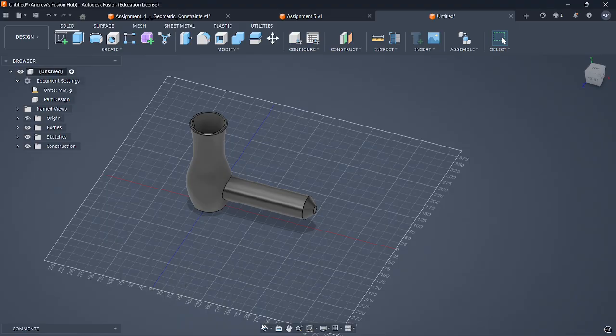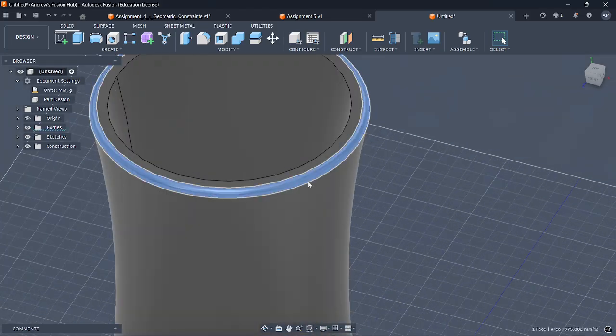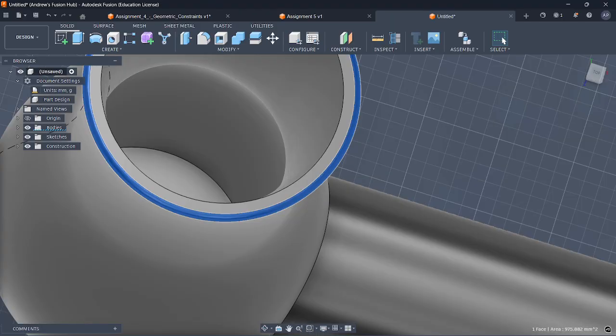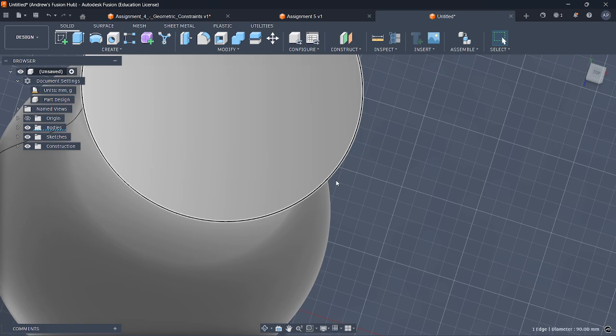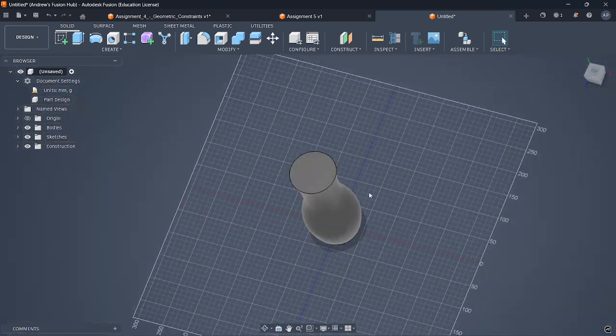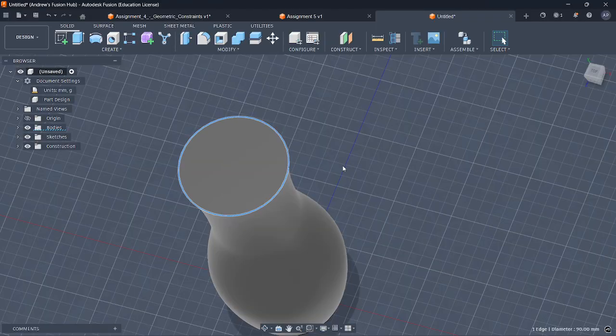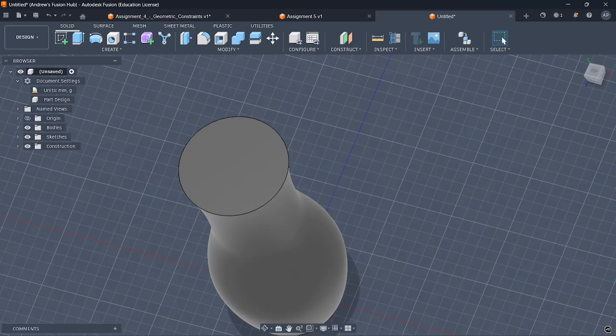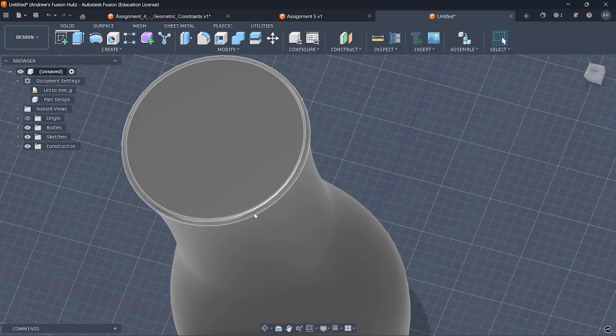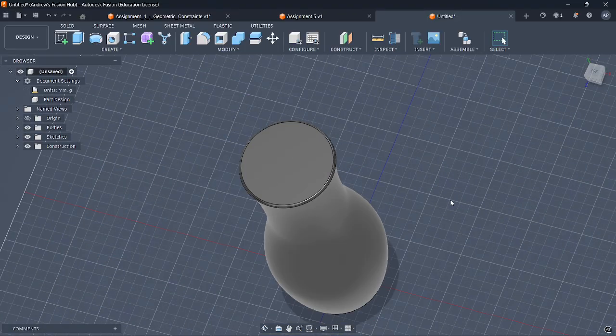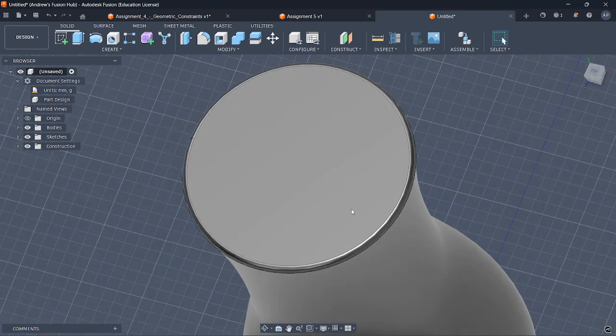So if I do the fillet at the end instead of as I go, then I won't make dependencies, right? Because if I fillet this, technically the outer edge that we filleted away doesn't exist anymore. And it's usually easier to just create dimensions and sketches off a clean face like this instead of something with more extra features that technically aren't necessary, right?